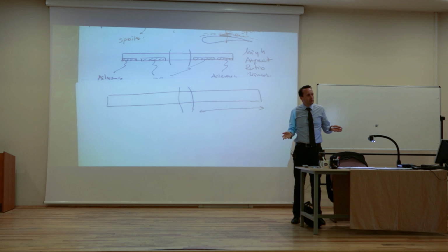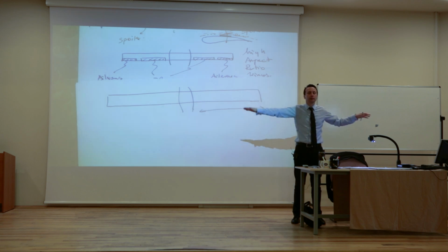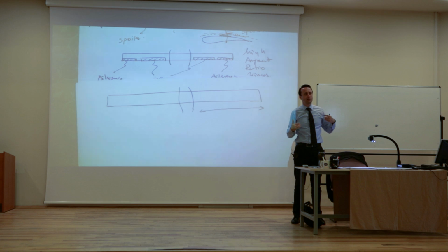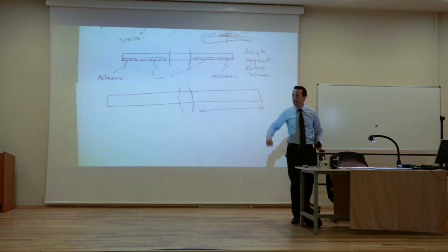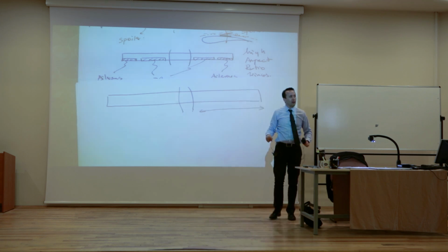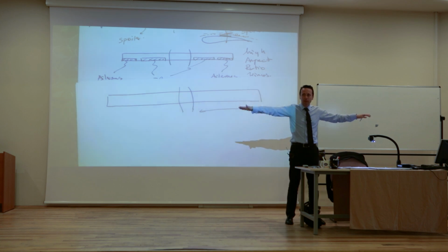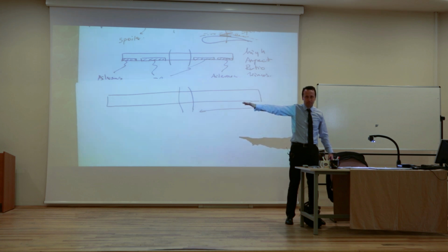So we don't want flutter, and we want to have these aeroelastic oscillatory modes somewhat in control. You see? We don't want to leave it alone. How could I control this movement on the wing? One way of controlling it is actually with ailerons. You can move the ailerons or oscillate them at such a frequency that it will counteract this mode. You see? You understand that?